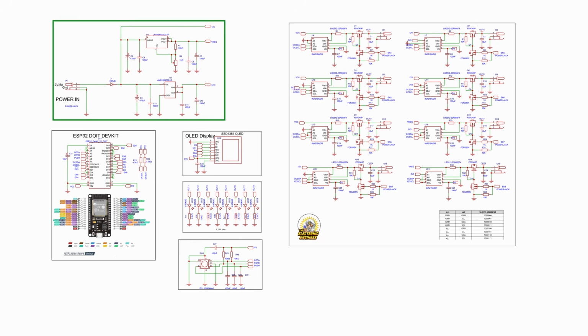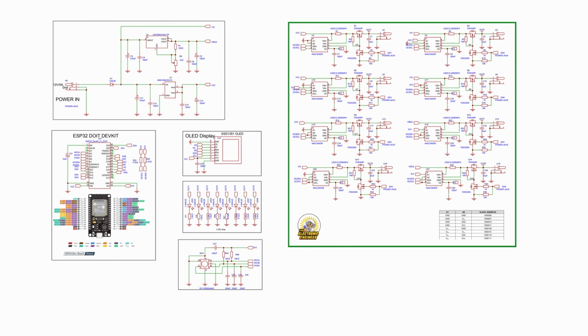It has two regulators to create a 5 volts and one that we can set, and it has a 12 volt output. And the one we can set is because some outputs are not 12 volt, but they have to be like 8 or for some occasions 7 or maybe 5, and you can regulate that using a trim potentiometer. Then we have a rotary encoder that I will use to program the user interface with, which brings me to the sections. It's 8 of them and they're all the same.